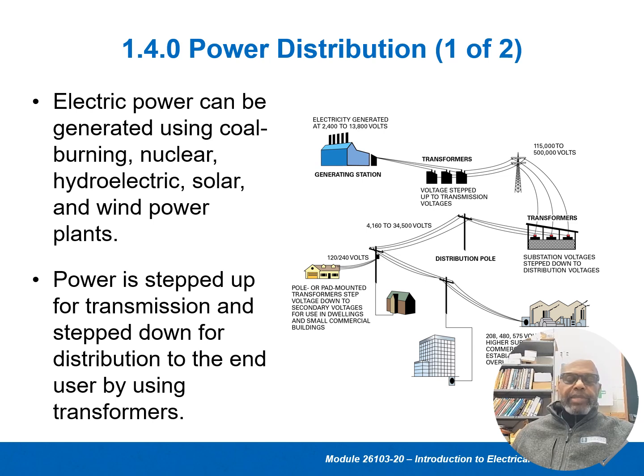They take that power and send it through power lines, distribution lines. Usually the distribution lines are at extremely high voltage, in the thousands, sometimes tens of thousands of volts. They send it up, boosting the voltage with transformers, through the power lines, sometimes hundreds of miles.